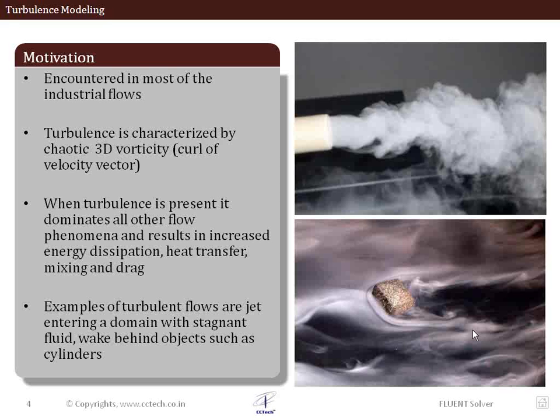That is, it has non-zero vorticity, and it leads to a lot of enhancement in heat transfer and transfer of any other property. So the flow properties get distributed within the domain quite efficiently if turbulence starts off in the flow.